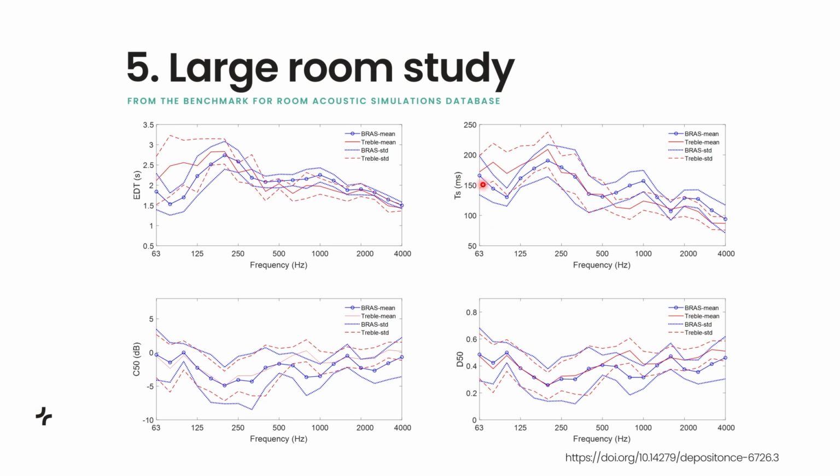The center time is also quite close, maybe off here in the lowest frequencies, and also for the early decay time there is some difference, which is most likely due to uncertainty in the material properties, as the authors of the database acknowledge that this is quite uncertain in this range. But overall, a very good match. We ran the wave-based simulation up to, I think, 500 Hertz, something in this mid-frequency range here. So, showing that we can do both large and small rooms very well.